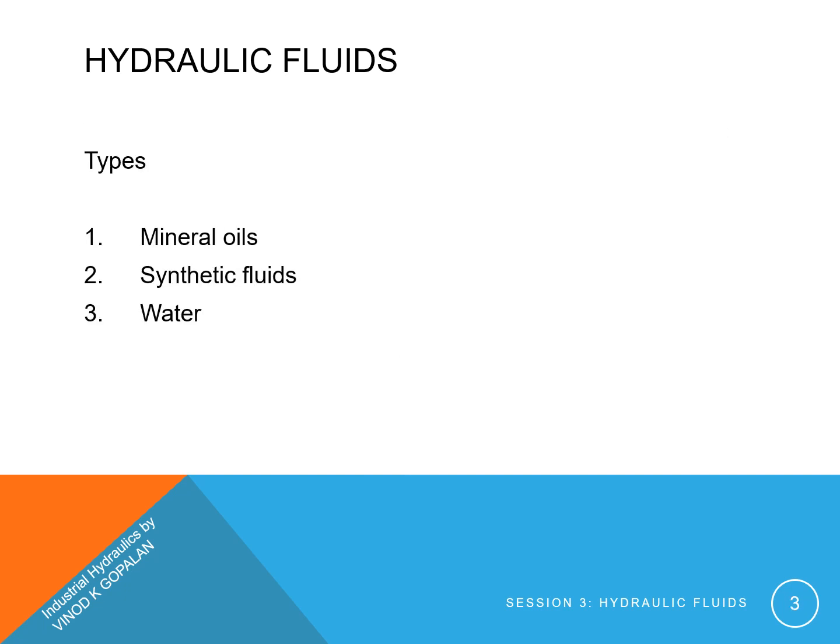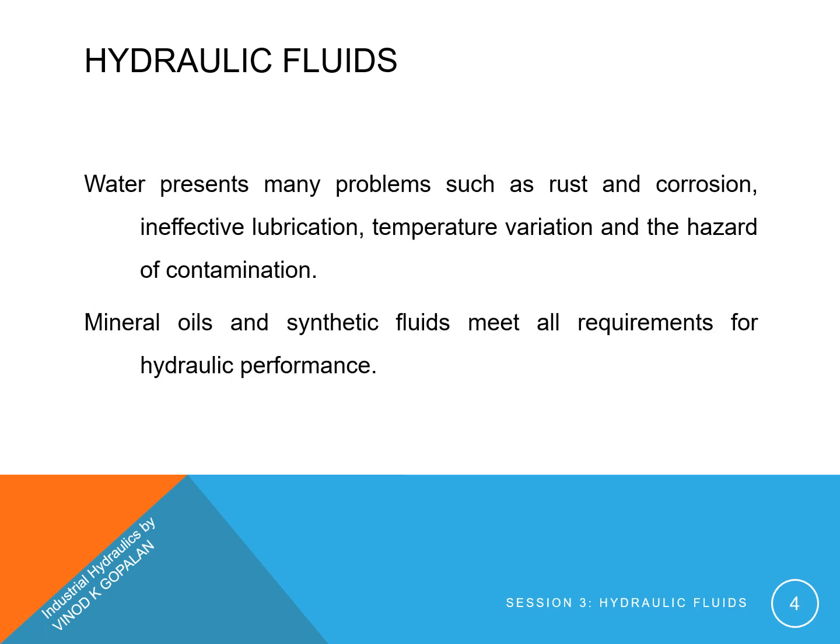Hydraulic fluids can be classified as mineral oils, synthetic fluids, and water. Water presents many problems such as rust and corrosion, ineffective lubrication, temperature variation, and the hazard of contamination. Mineral oils and synthetic fluids meet all requirements for hydraulic performance.